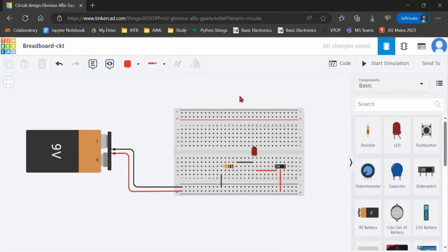So we'll be using this breadboard to utilize the basics of connection, because we will be having two different wires in the lab. Once you want to connect the wires, you just place these wire terminals into these holes and they will be connected by default. Like a resistance will be at two different terminals; by bending it, we will place it into two different holes, here and here, so it will get connected. Likewise, we will be utilizing the breadboard to make the connection. So this is the basic connection.